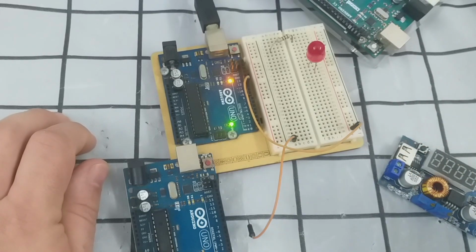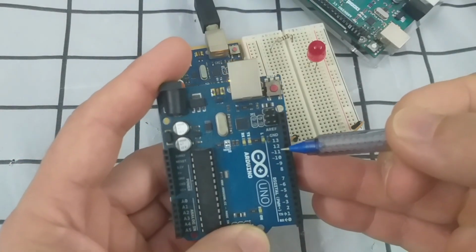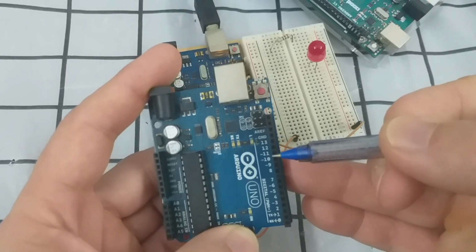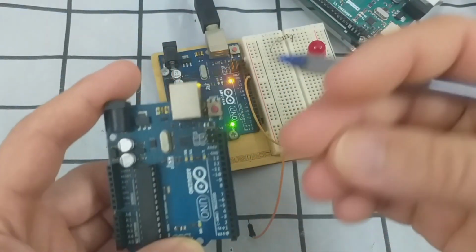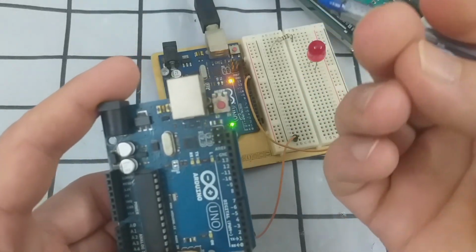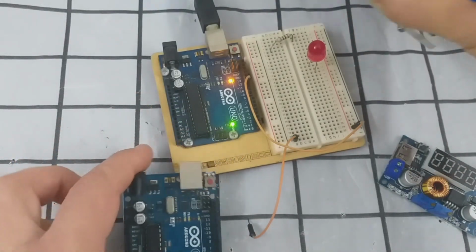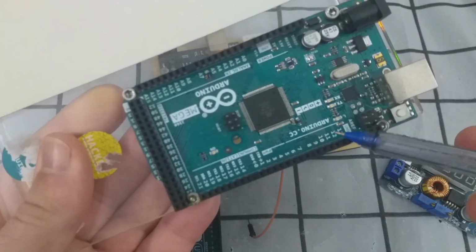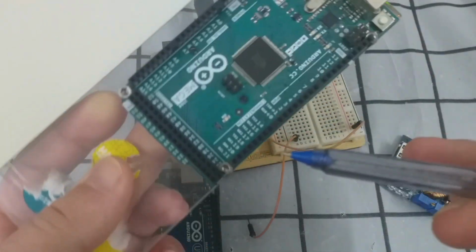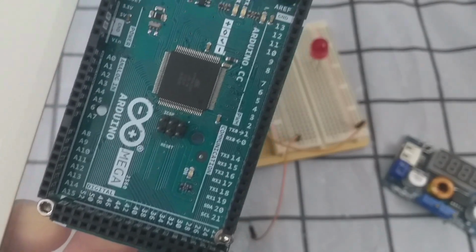which means they have no capability to output a variable analog output. Therefore, we will make use of the available pulse width modulation pins in the board to convert them, filter them, and buffer them, which then at the end generate the variable analog output. Okay, so you can see here these Arduino boards have the capability of generating PWM signals.